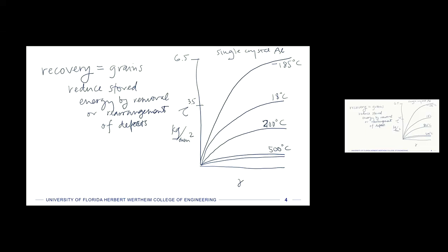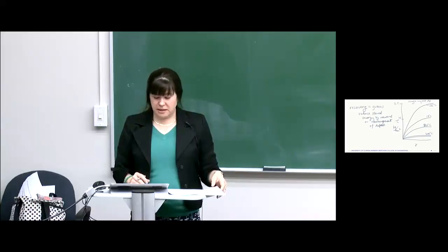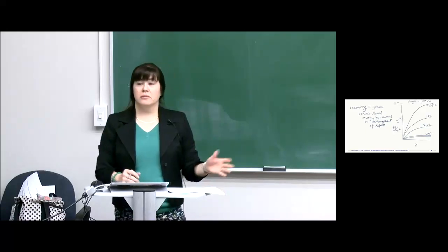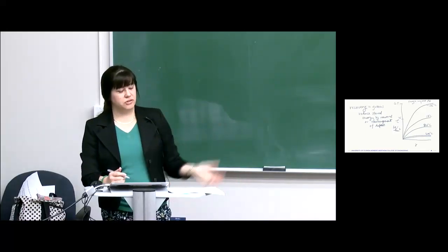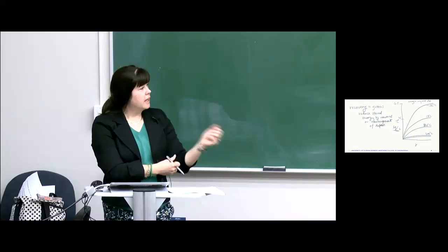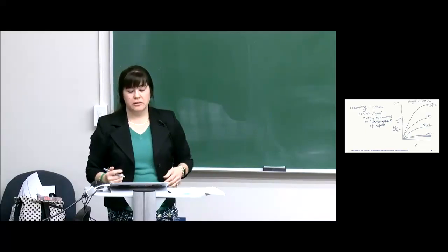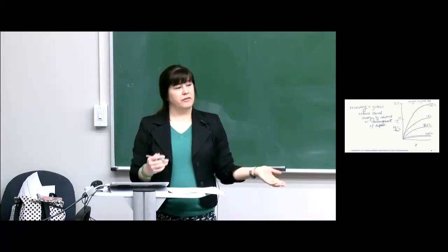So the extent of strain hardening is related to not only the type of material and its crystal structure, but also the temperature it's at and its ability to recover. Okay? And so these are concepts that are introduced in the book in chapter 3 because they're related explicitly to these atomic origins of plasticity. But we're not really going to use them again until we understand stress states and have some failure criteria in mind, and then we'll talk about how these effects go there.